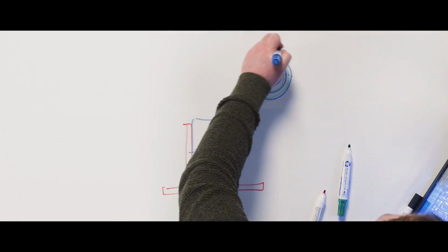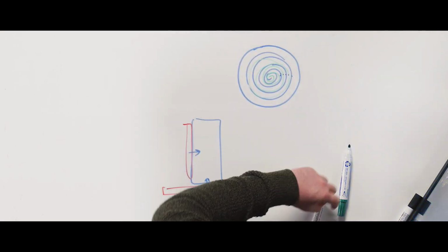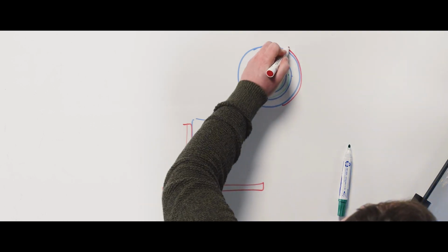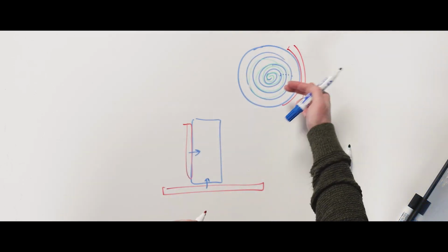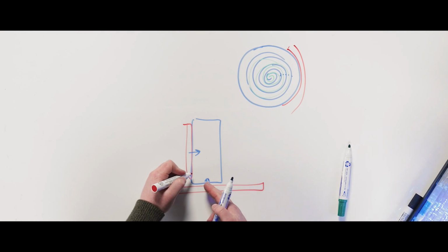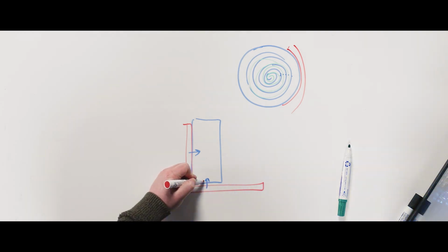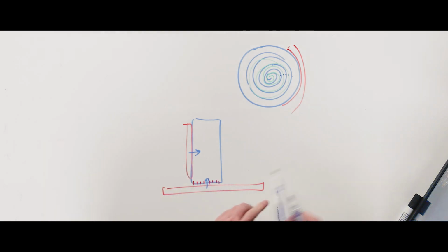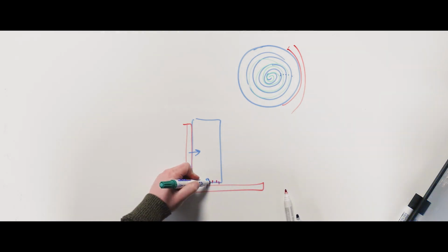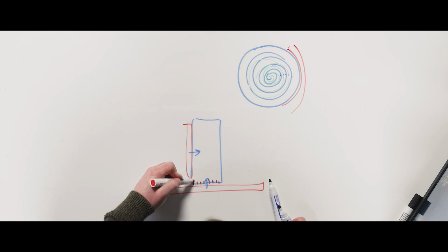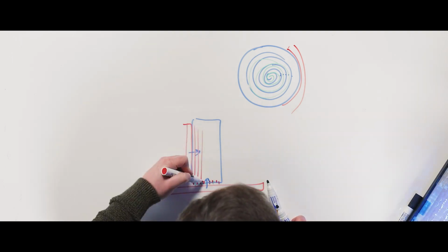So that means that when you cool the battery cell wall with your heat exchanger, the theory is that it's not as good to cool from the side as from the bottom, because at the bottom of this, you've basically got very conductive, very conductive, very conductive, and so forth here, as well as the insulators. So you'll get higher heat transfer up through the battery cells.